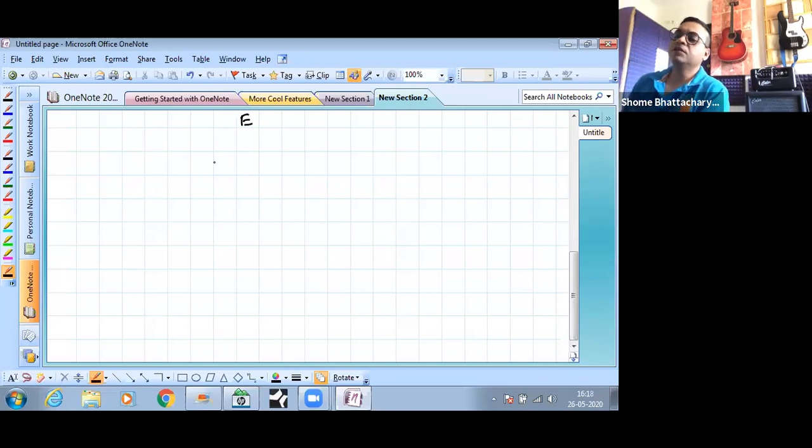So for that type of typical transistor, the device design is something like this. You have a narrow in radius but large in length kind of cylinder, which is in contact with a comparatively thinner cylinder like this, which is in contact with a comparatively medium thickness cylinder but of much larger base radius, that kind of thing. So this is your emitter pin. The cylinder in the middle is the base, and this is the collector.